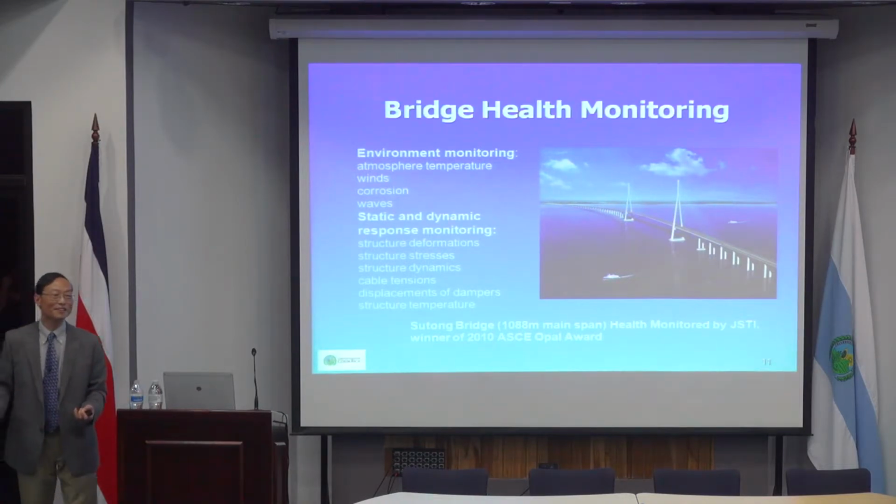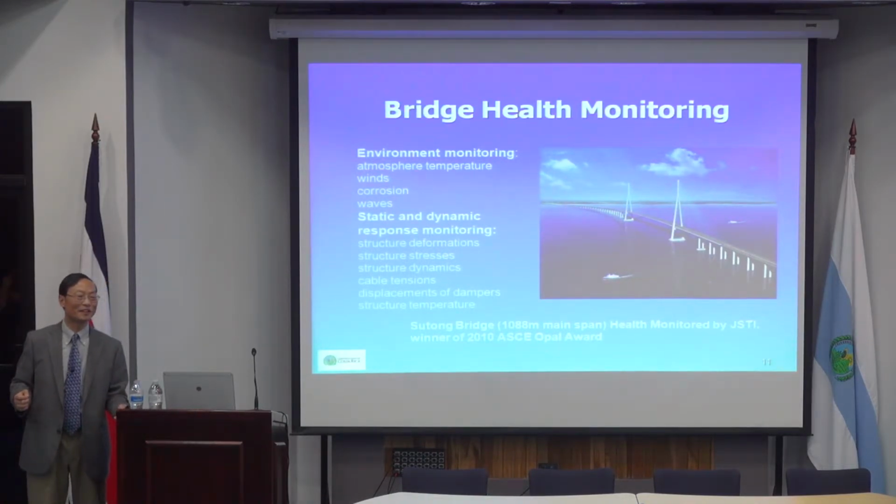But there's another measurement which is very important and very good, in my knowledge, which is vibration-based. We all know the magnitude of vibration is related to loading, but the frequency of vibration has nothing to do with loading. Everybody agrees on that part.